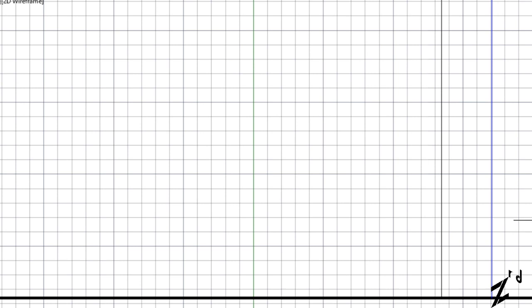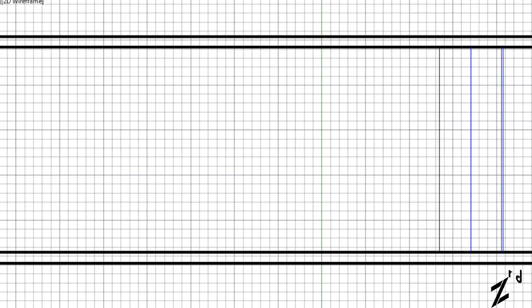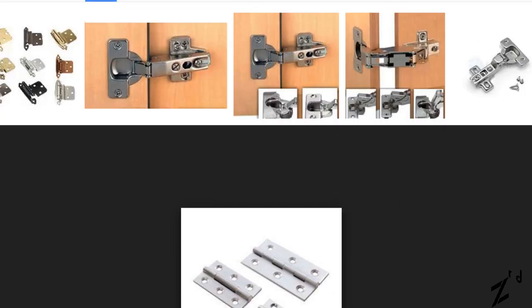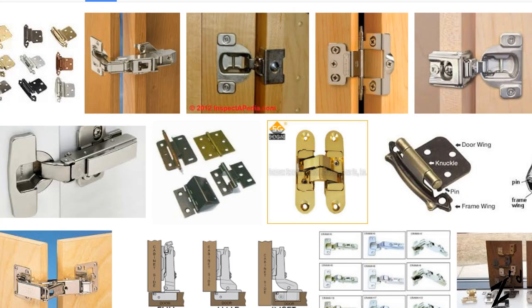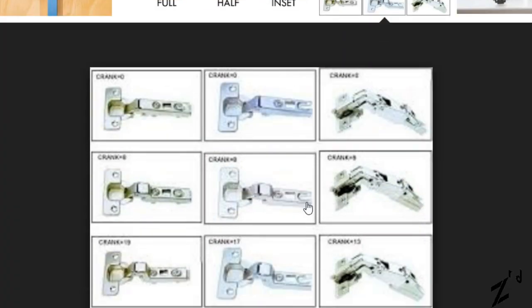And when I say designed, I mean the material selection will have to be considered. You get edge tapes you can put for that, or the carpenter might have to cut a very thin strip of laminate to stick onto that, which are generally not very clean finishes. It has been done for a very long time, but it's not a very clean finish. And the way we get around that is by the clever use of hinges. And the hinges that we are talking about, I'm going to just search wardrobe hinges types, which would give us a picture which is nice.